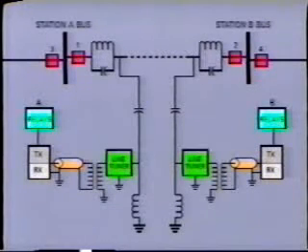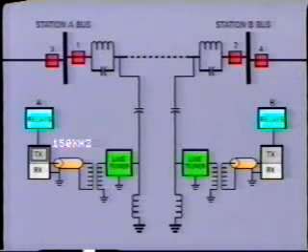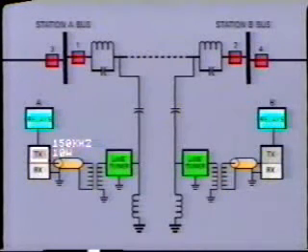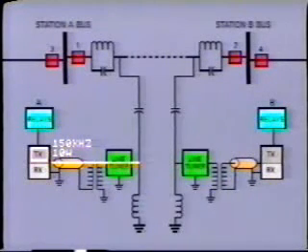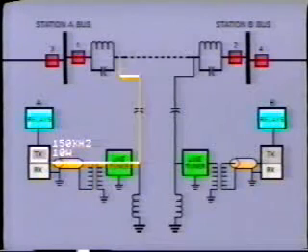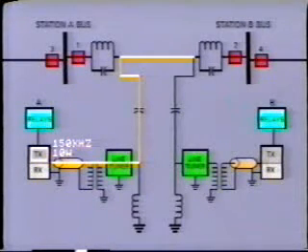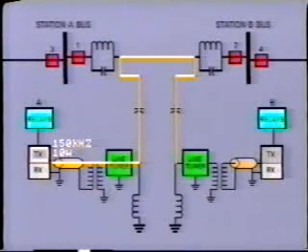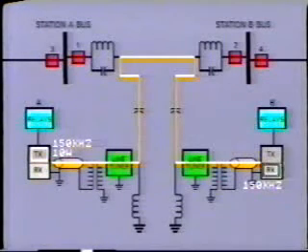When the protection relay at station A operates, it switches on the transmitter, which is already tuned to send a signal at the desired carrier frequency, say 150 kilohertz. The signal power leaving the transmitter will be typically 10 watts, but other levels of power are also utilized. This high-frequency signal passes through the line matching unit, the line coupler, along the transmission line, through the coupling equipment at the far end, and into the receiver, which is set to the same frequency.